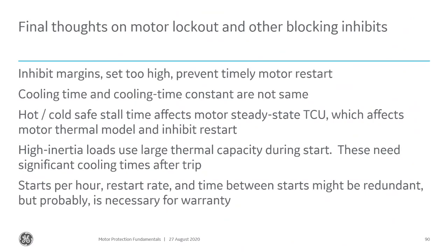High inertial loads use large thermal capacity during the start. These need significant cooling times after a trip. And the starts per hour, restart rate, time between starts might be redundant, but probably is necessary for your warranty. Okay.